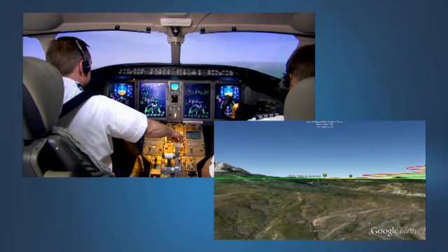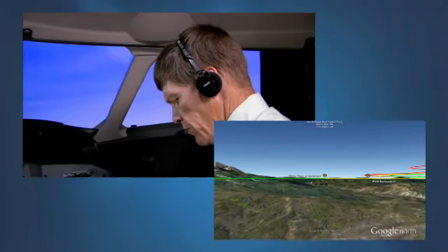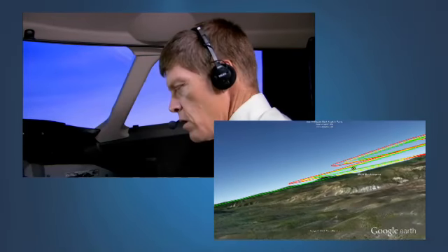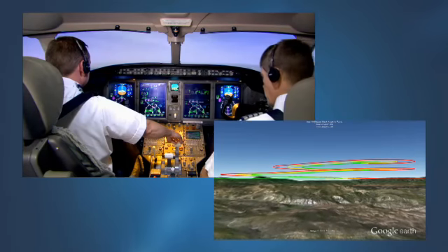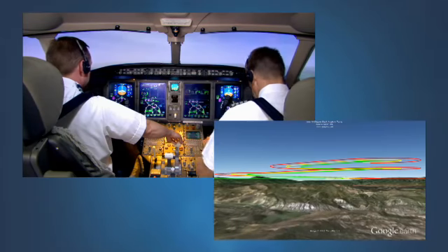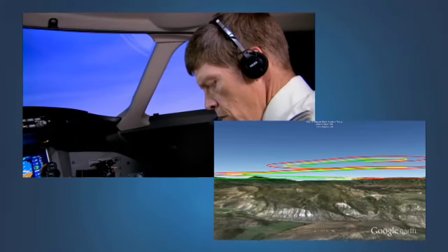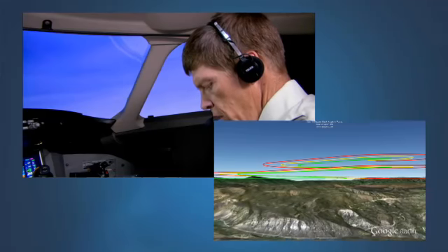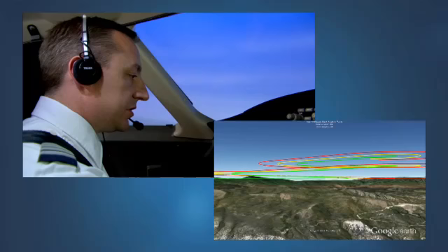Rudder trim as required. Electrical load reduce. Bleed switch off. Cross flow open. Anti-ice off. Monitor fuel balance. Cross flow is required. Transponder goes to TA only. Land as soon as practical. Next is the engine air start procedure or the single engine landing procedure. Your choice. We'll do the engine air start. There's no reason not to.